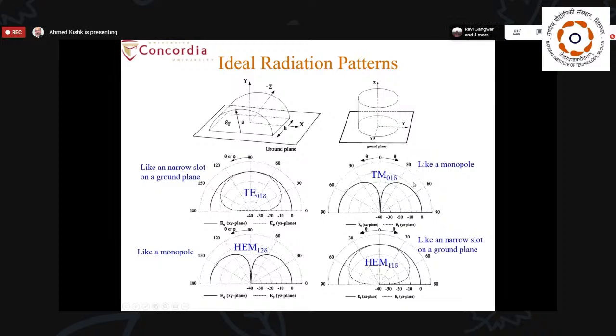So one has to really know in advance what the dielectric resonator resonant frequency is for the TM01 mode, in order to operate at its frequency, not at the resonant frequency of the monopole loaded with dielectric material. Also, the HEM12 mode, although it has phi variation, the phi variation is in this direction.